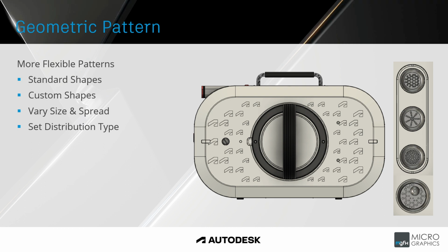Moving on to geometric pattern command. This allows you to create more flexible patterns within Fusion 360. You are not stuck with using just a standard rectangular or circular pattern. The nice thing with this is that you don't have to have any geometry to start with. All you need to do is start the geometric pattern tool and pick a face. There are standard shapes that can be patterned on that face. If we have a look to the far right of the slide, we have 4 options where we see different geometric patterns using a sphere to cut out a dimple in those components. The bottom one is a cylinder, but we can choose those standard shapes to pattern across a selected surface.